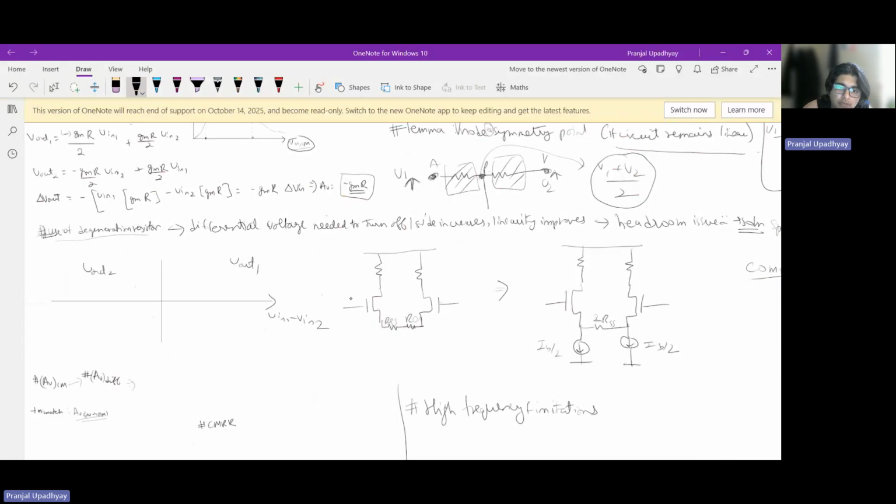We said that if I'm exerting some excursion here, okay, this node's voltage I can find as the average of these two excursions, right? Because the circuit follows symmetry. And so since in differential signaling, if this is V, this is minus V, the average is 0 here, so I can ground this node in my differential small signal analysis, right? Which is quite amazing.